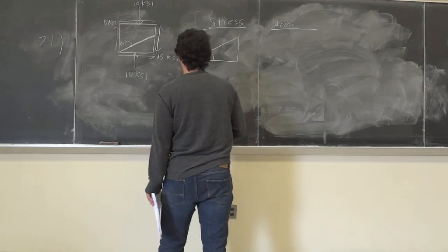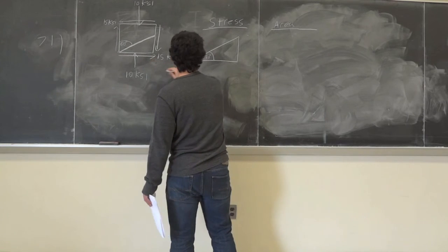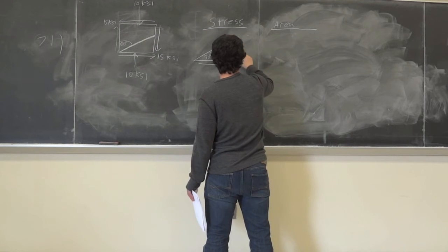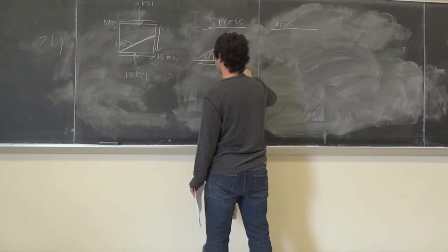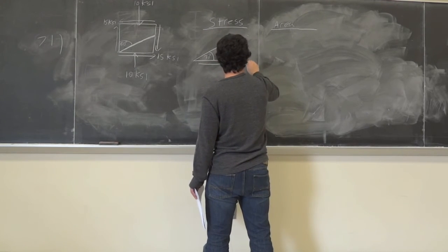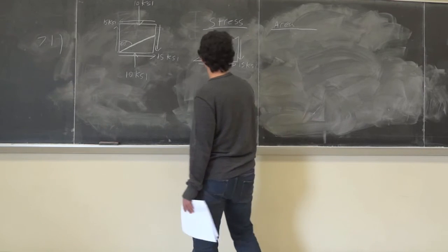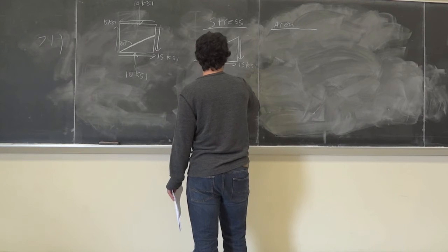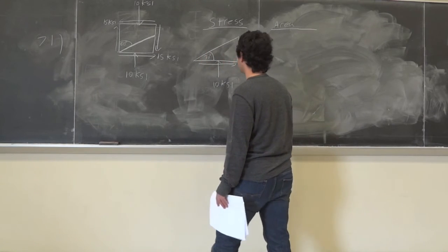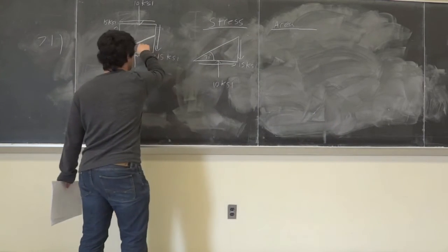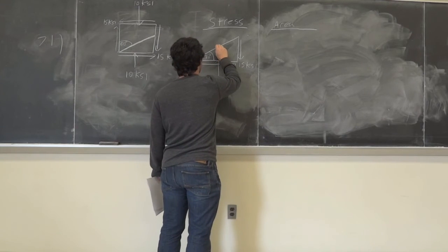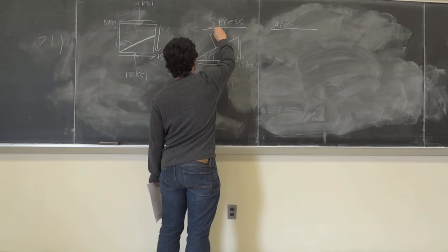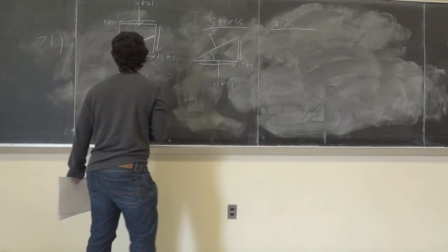All right, so let's draw the stresses. You're just copying this onto this triangle, right? So you have this shear stress, tau xy, it's 15 ksi. And then you have this sigma y, 10 ksi. And now you have stresses in this section. So you have a normal stress, and you also have shear stress.